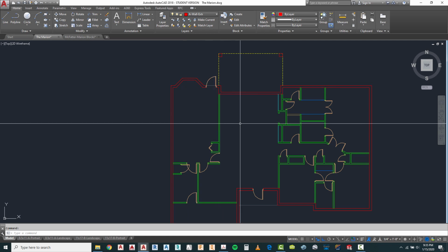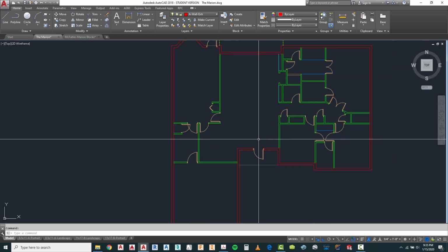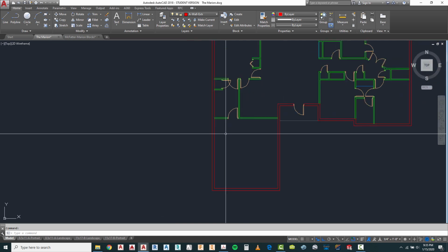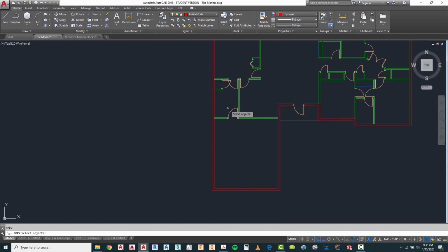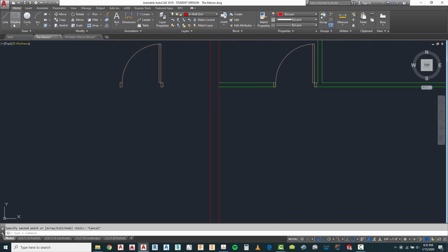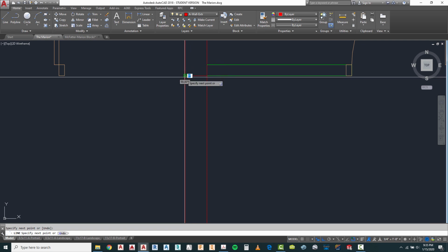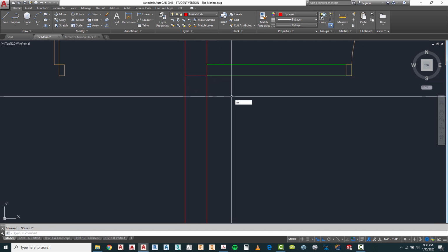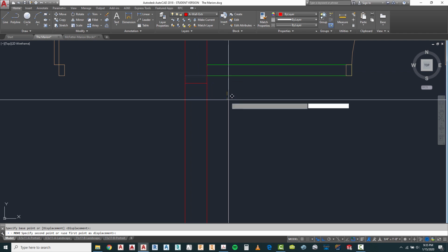So now we've got most of these located. We're doing pretty good with that. Let's go ahead and put another 3-foot door that's leading out from here. So I am going to first copy a door, getting ready to put it in there. And I am in A wall exterior, which is where I want to be. And I'm going to start this opening. I'm going to move this guy down about 8 inches.